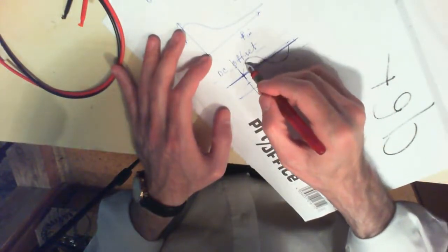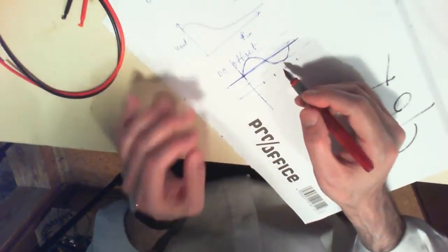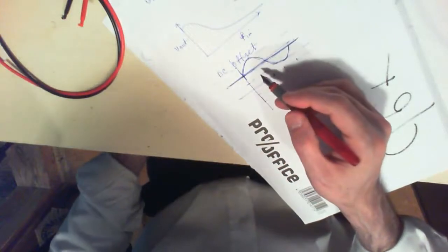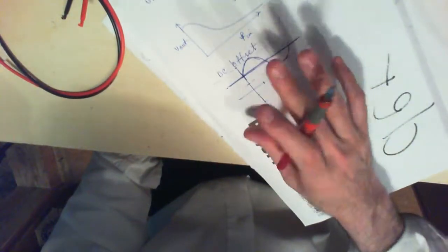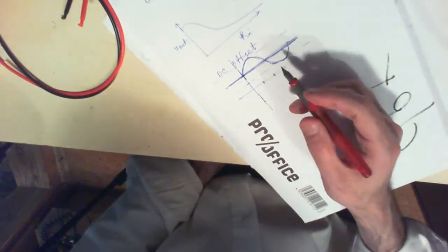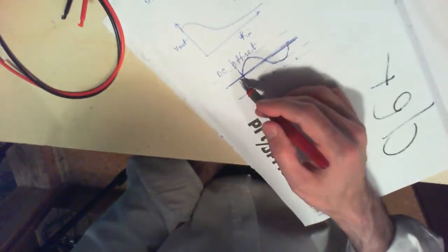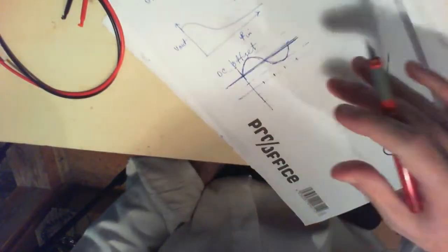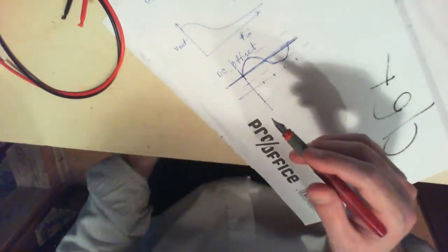Okay, so you would have an AC signal on top of this DC voltage over here. There are many different types of situations and circuits where you would have this. For that reason, they have put that in all kinds of signal generators, and the signal generator can give you a DC voltage, and on top of that voltage some signal is riding. So then you can do all kinds of experiments using this kind of situation.